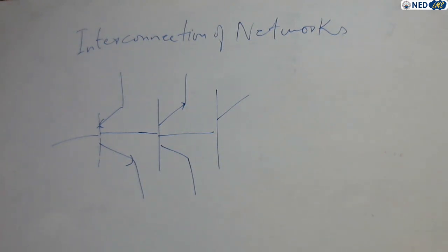When the networks are in parallel, their individual y parameters add up to give the overall y parameters, because y is the opposite of z. So y is treated in parallel like z in series, and vice versa.